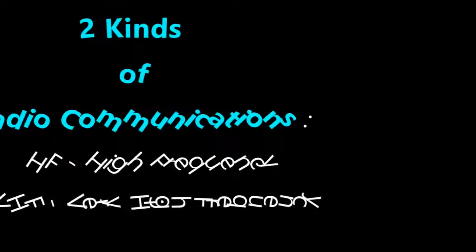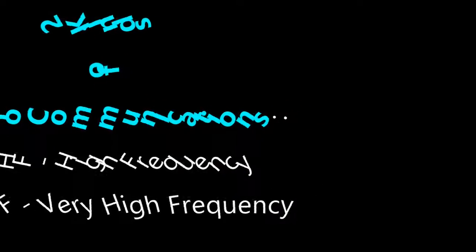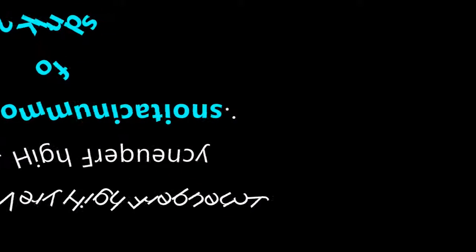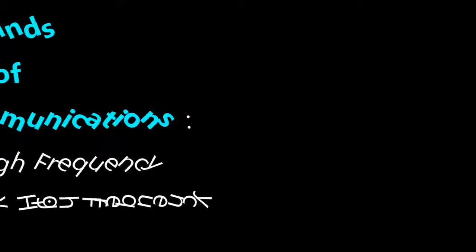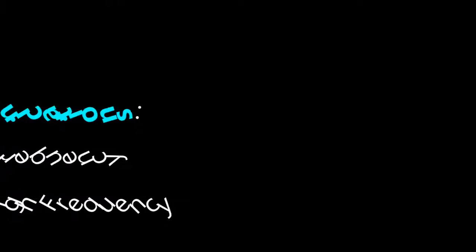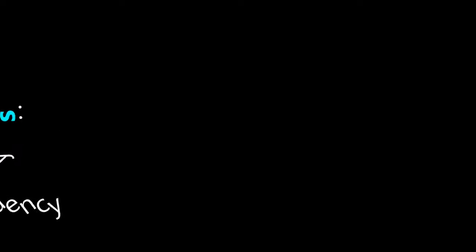You may see this on a test. The radio management panel, the RMP, can actually serve as a backup for your flight management and guidance computer. Remember, the radio management panel is in charge of not just speech, but also helping with navigation, managing the communications frequency control for radio navigation.